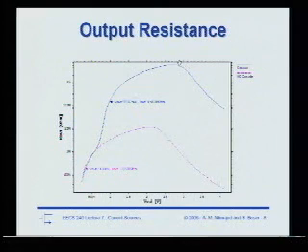Now, if I put in a cascode, something very interesting happens. First of all, we get that huge 1 plus GM times RO boost in the peak value. As far as the swing goes, now you're shooting for a higher output resistance, let's say you're targeting a gigaohm, so you have a much smaller swing compared to here where we're just going for a megaohm.